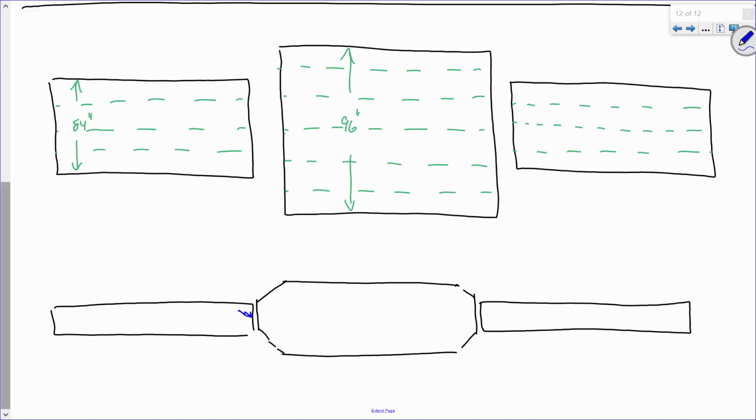You're going to have to weld you some runoff tabs. Then you're going to have to grind off those runoff tabs. Then you're going to have to take this, pick it up, put it somewhere, and then do all that again, for the number of flanges that you have. Instead of doing it all at once, now you got to do it how many different times? It's going to bump up the fabrication costs, right?